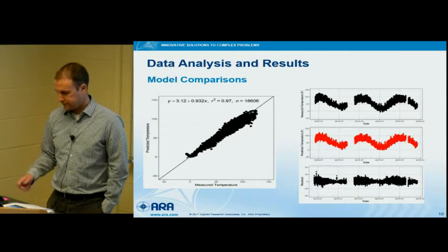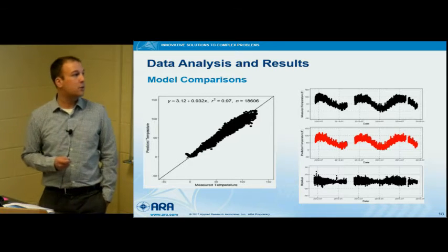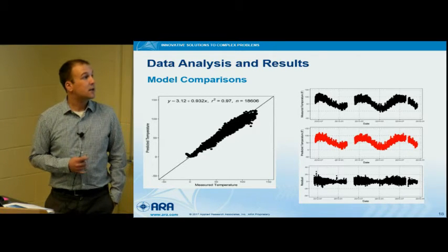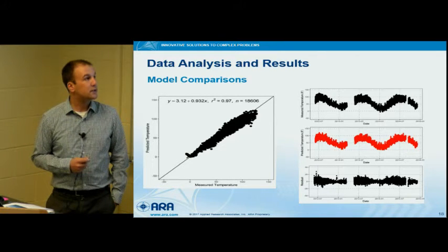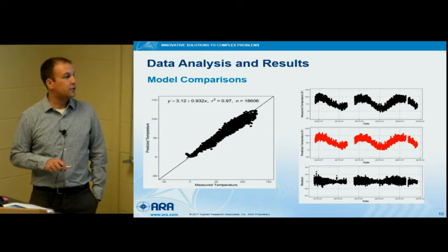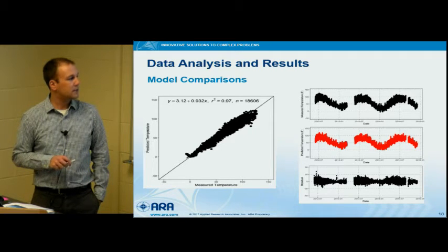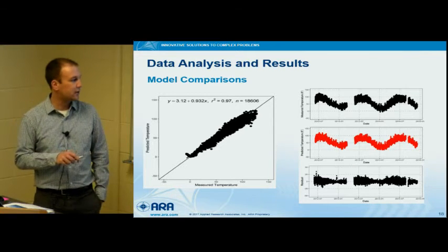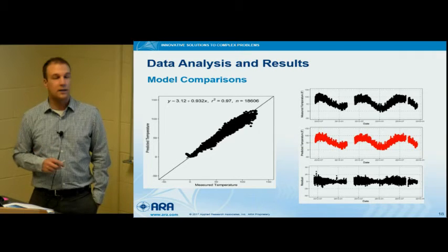All right. So now here's an example of one site. I'm pretty sure this one is an IDOT site. So you can see it's a fairly good prediction between the predicted and measured. This little area is a little strange. There's something in the EICM that we had to change to make sure that gets corrected, and you'll see that later on.